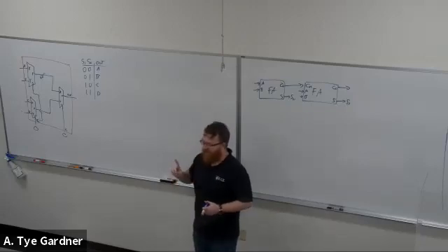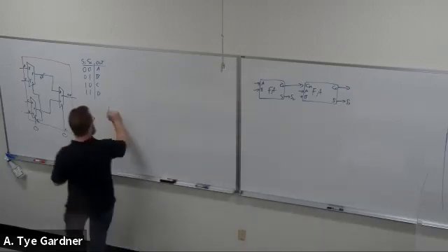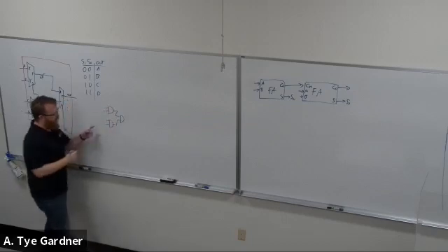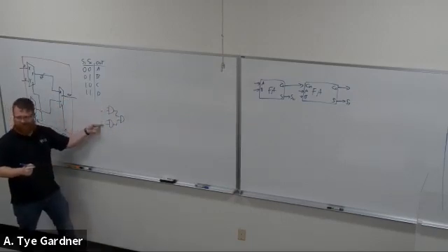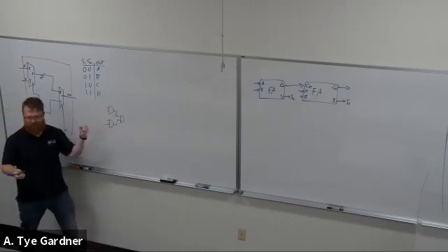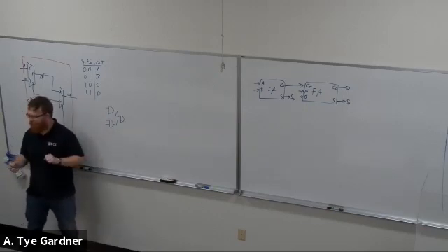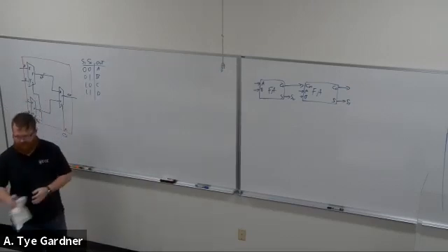It does not care about the order of statements, right? If I draw up AND gates, and I were to write code for this A, B, C, D, it doesn't go this gate, and then this gate, and then this gate, and this gate. That's not reality, right? They happen all at the same time. They change if I change them close to instantly, right? They have a delay, but close to instantly. So we need a language that reflects that reality.